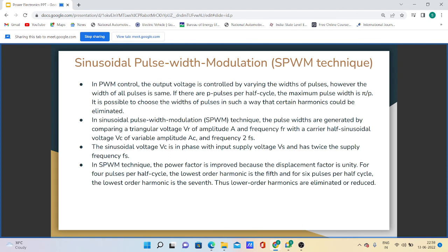Sinusoidal pulse width modulation is a technique of pulse width modulation used in inverters. An inverter generates an output of AC voltage from an input of DC with the help of a switching circuit, to reproduce a sine wave by generating one or more square pulses of voltage per cycle.